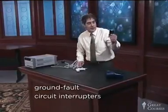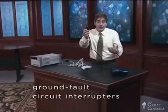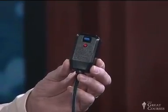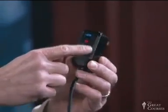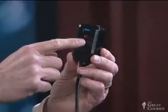You want to be even safer, you use devices called ground fault circuit interrupters. Here's one that's built into a hairdryer, because a hairdryer would be used typically in a wet environment of a bathroom. Many of them are also built into electrical outlets. You'll see outlets in bathrooms, particularly near swimming pools, in basements, outdoor outlets that have these extra buttons that are for testing the ground fault interrupter.